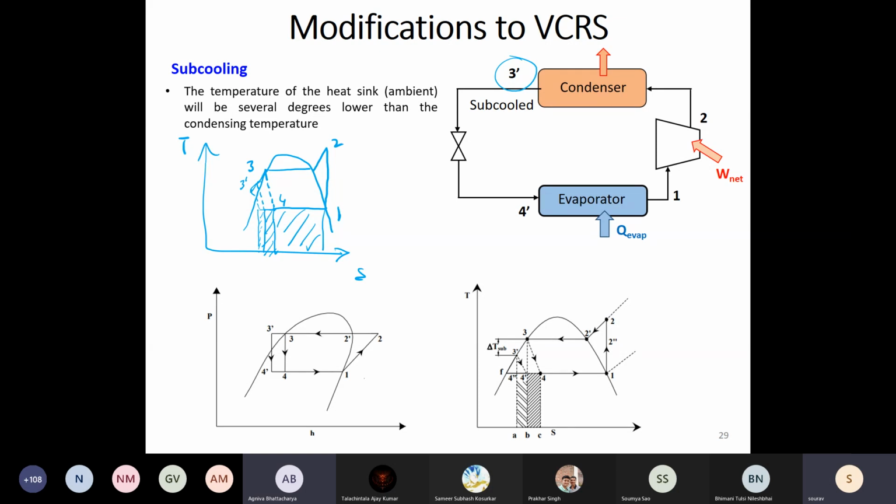So a 3 to 4 degree C temperature difference will remain when compared to the ambient. Now, when the same AC is used in peak summer, it would be around 45. So if the ambient is at 40, my condensing temperature could be around 45. I will not be able to go below that.